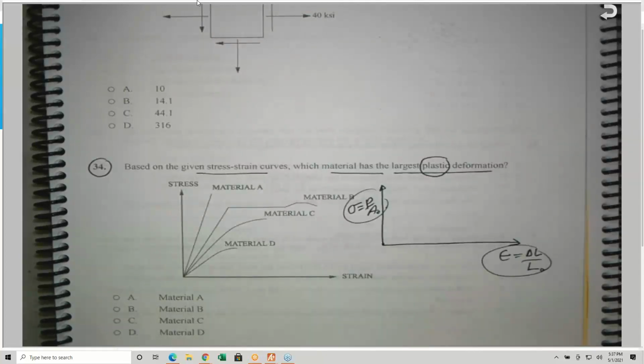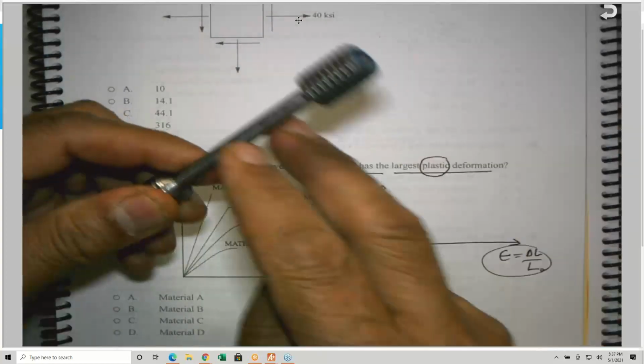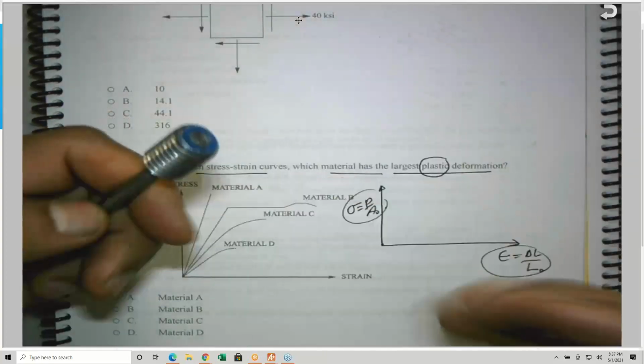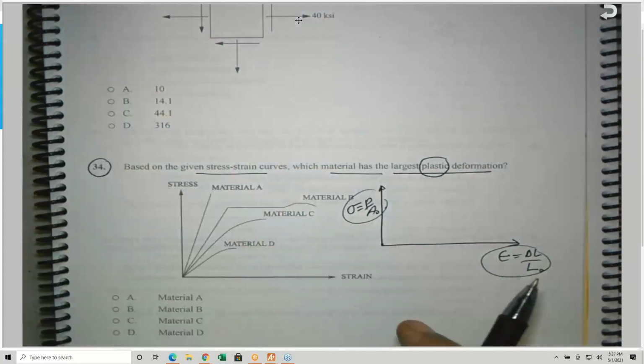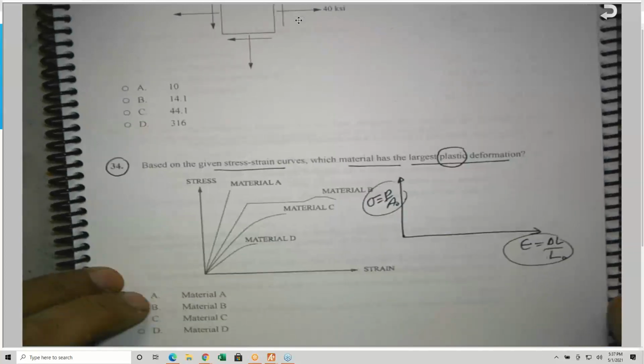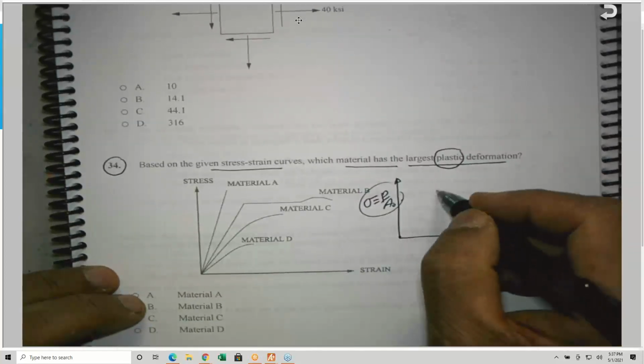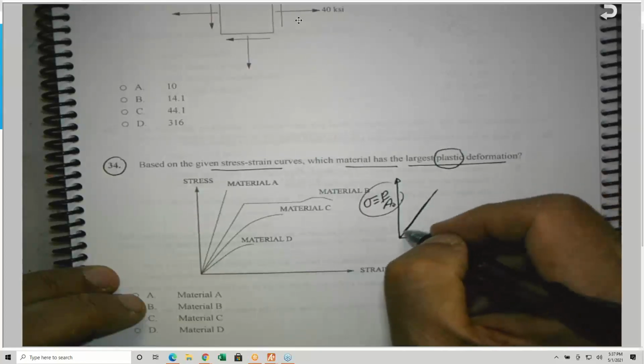Because if you like to do the true stress and the true strain, you have to be continuously measuring the diameter during the process of testing, and this is not really convenient. And this is one reason. The main reason, by the way, is that the true and the engineering are essentially the same during the elastic stage.